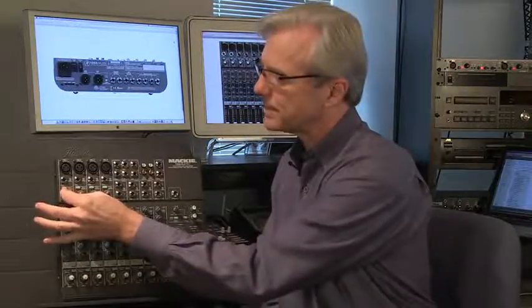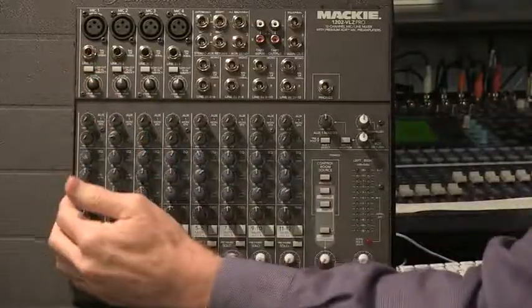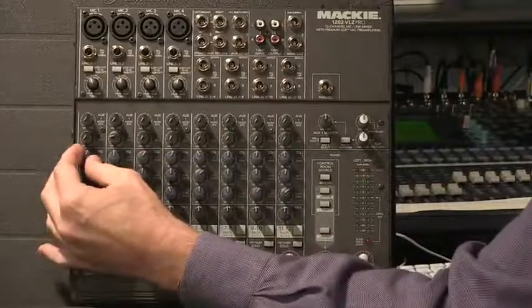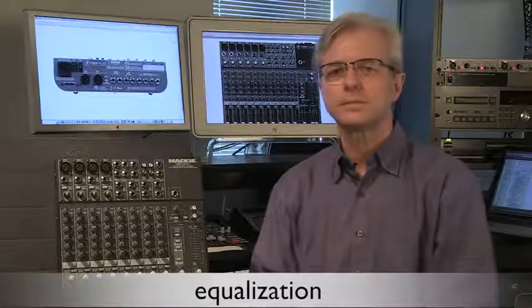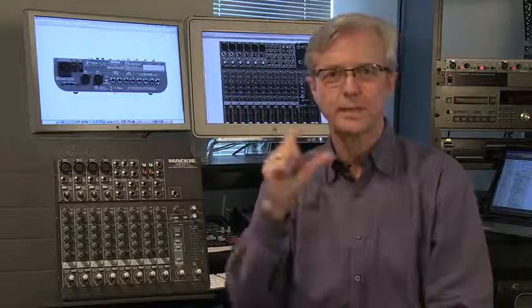Once the preamp is set correctly, then we look down here for the next set of controls. These blue knobs here are all affecting what is called equalization. Equalization allows us to divide the frequency spectrum. Remember, our frequency spectrum is from 20 to 20,000 hertz. An equalizer allows us to amplify or attenuate various ranges of that spectrum.